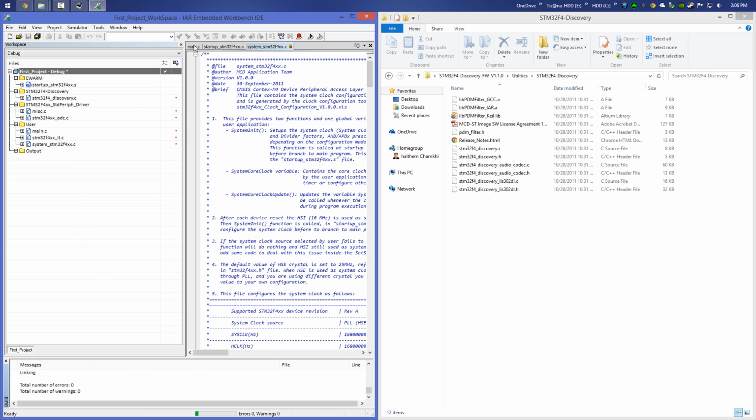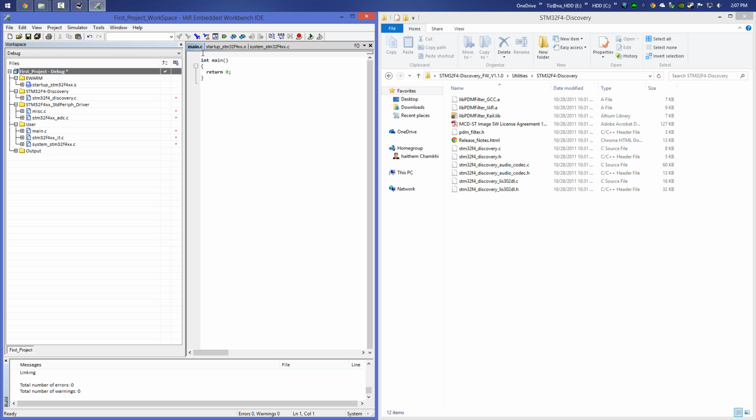So now before finishing the header files, we go to the main. We're gonna include 2 header files. So we write include STM32F4XX header file. We saw it earlier, this header file contains the register definition and the memory mapping of our microcontroller. And another line, we include the STM32F4 discovery header file.